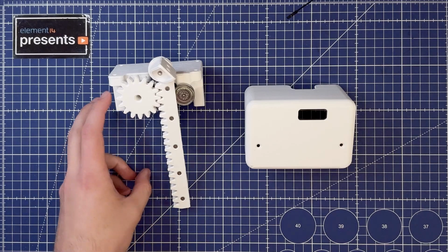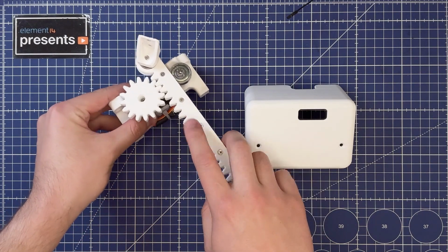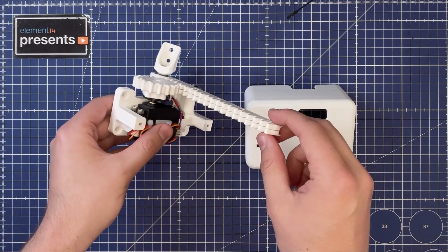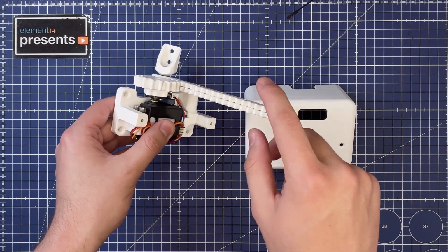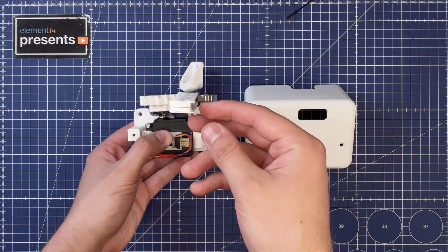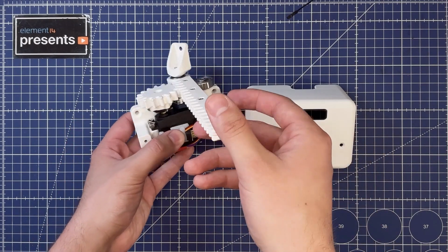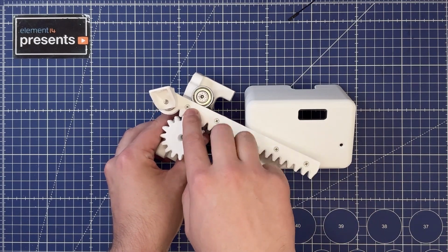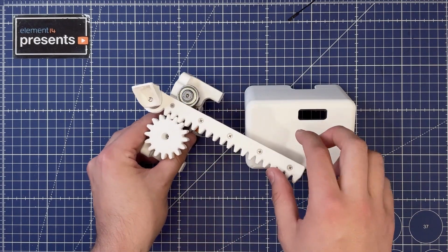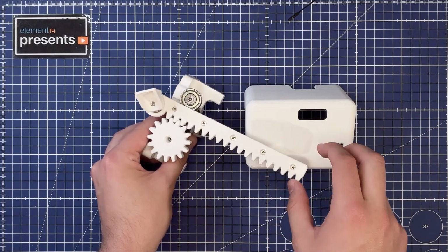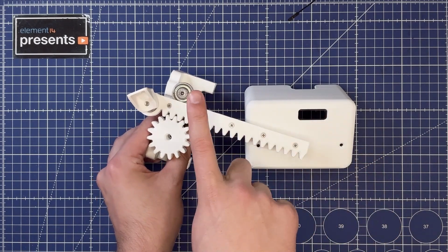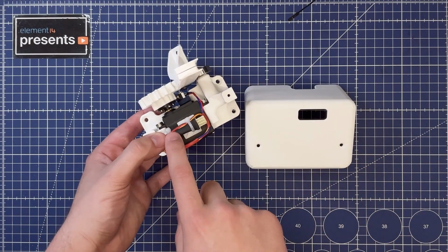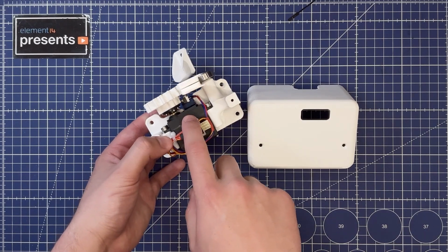And this is the assembled window actuator. So you can see the rack gear and the pinion gear. So as you've seen from the CAD model, the rack gear is actually made out of two parts because of this guide rail, so that there's no support material. And there's just a single bearing here to keep it in line. I didn't want to use two bearings because I want some leeway in this direction, because the window changes angle as it moves. Besides that, it's the same as the Venetian actuator.